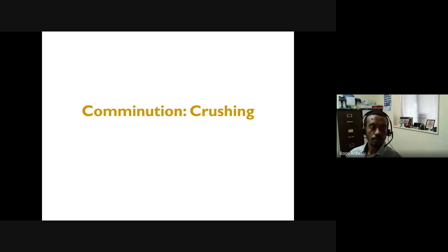So as I was saying, I was teaching you some background information about the critical things we do in a mineral processing operation. Sampling is very critical, and needs to be done properly before you send samples for assay. You need to know how you do your particle size distribution, because that is probably the only way to measure your crushing and grinding performance. So it helps to develop a proper method to do particle size distribution.